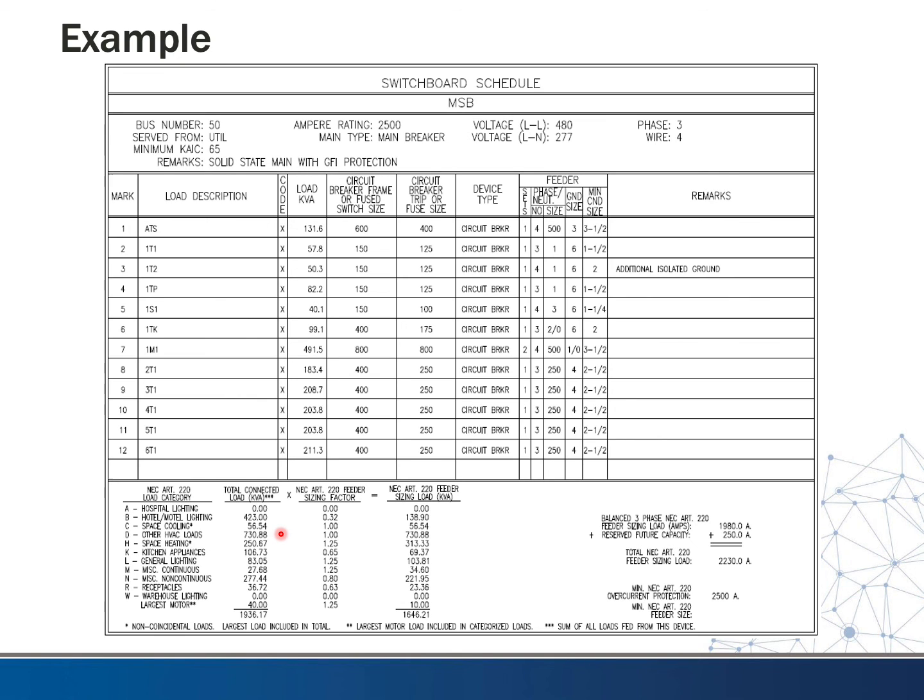I couldn't take the higher of the two, and in this case there was some space heating that we anticipated would run for 3 hours or more. Sometimes they'll put little space heaters in the stairwell and stuff like that, and that many times can run for longer than that, so we did have to bump that up. They did have a small kitchen, and they apparently had 6 or more appliances in there, so I got to use the maximum diversity factor there, 65%.